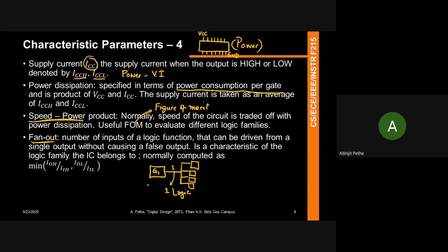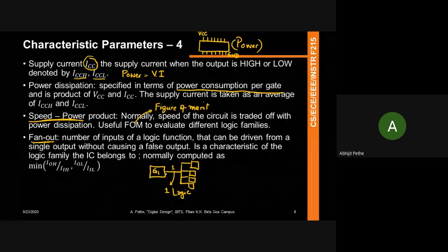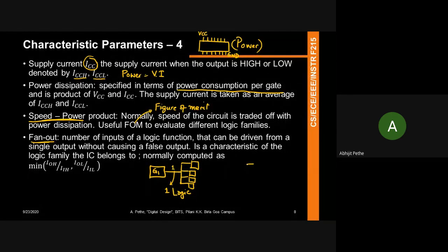Okay. Prayas asks, can you repeat what fan in was? Okay. So fan out, everybody understands, right? Now fan in is, normally when I say fan in, it means how many inputs can be connected to a gate, right? Suppose it's a 3 input gate, it means the fan in is 3. So fan in is not something that you have flexibility over as a designer, right? Because fan in is something which you have designed for. So if you're buying a chip, the chip already gives you a certain fan in.